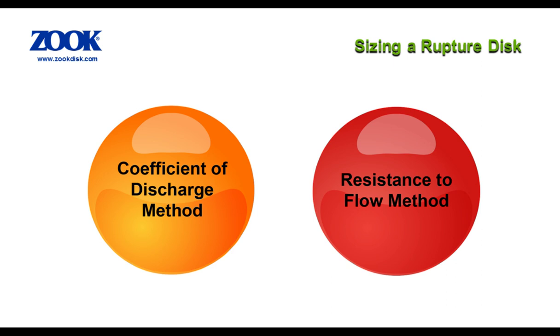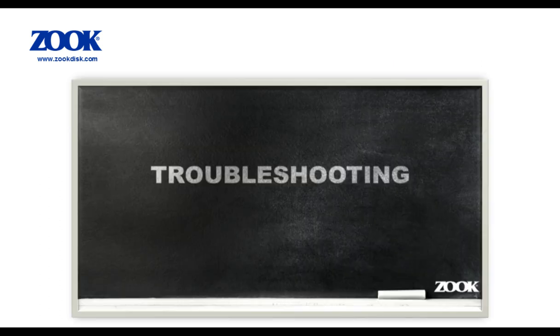For resistance to flow sizing, the additional rupture disk device is accounted for by simply adding it as another component in the relief system. Because a rupture disk is a differential pressure relieving device, pressure cannot be allowed to develop in the space between the two devices, and a pressure gauge, tri-cock, free vent, or suitable telltale indicator should be installed to permit detection of disk rupture or leakage.